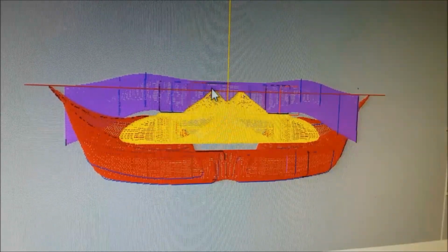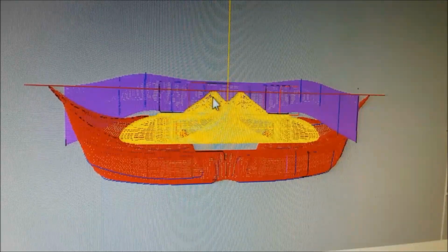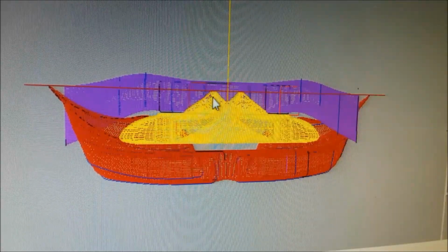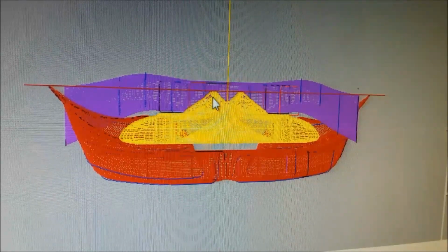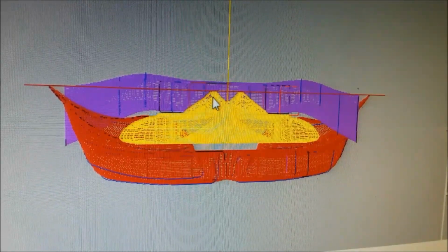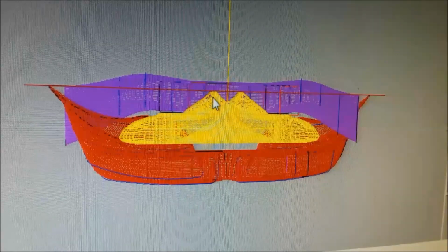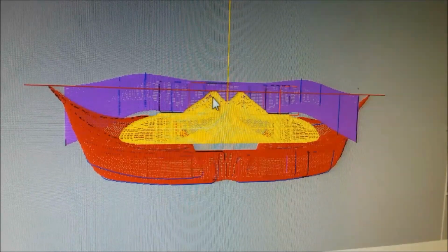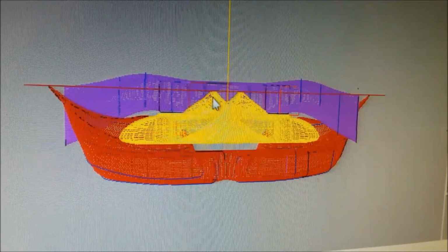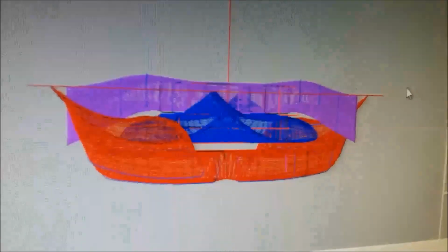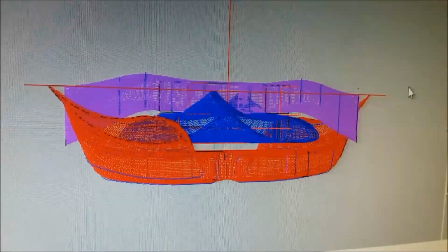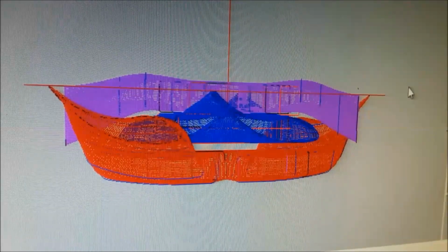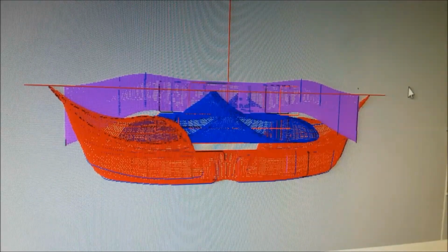So they're not robbing air from the following blade, which has to work in a lower pressure, which means that the lower pressure tries to bend the blade up. As it turns round and round, it tries to tilt your fan on your ceiling. And that's why it's wobbling. They're all on right now. If I had one off, we take masking tape and put it on the tips of the blades and number them 1 through 5.